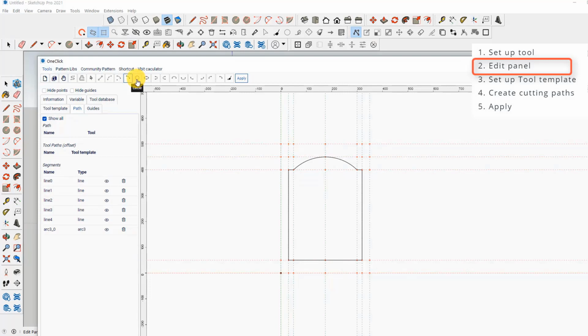For circle tool, select it, select the center of the circle, enter the radius value, add new. For ellipse, also select the focus of the ellipse and type in Rx and Ry values, 200 and 100.